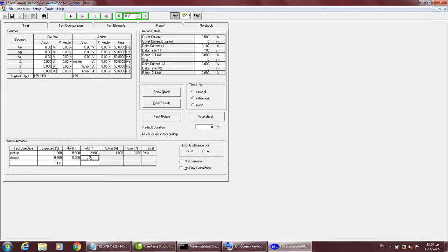Earlier we defined how to ramp that. So from here the other ramp function needs to be defined. Till here we already defined. Now first is wait. After picking up the relay, if you want some time at 1.1 ampere, it will remain for that time. If you do not require it, then leave it. So it is 0 now.